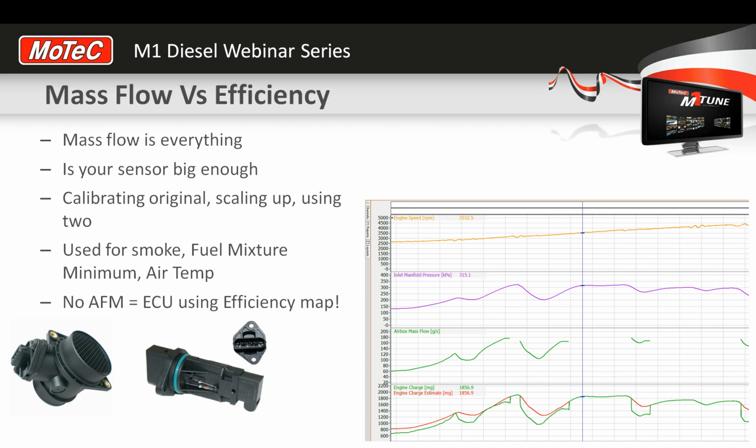Or, at that same boost point, the vanes on the turbo can be open because there's a higher volume of fuel being entered, and if those vanes are open and the exhaust back pressure is low, you then have a way more efficient engine. It flows more air. So what that means in effect is that manifold pressure is not really a good way of determining a consistent, plottable, repeatable airflow in a diesel engine.